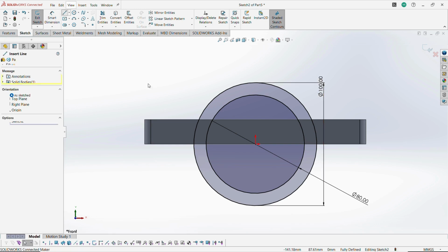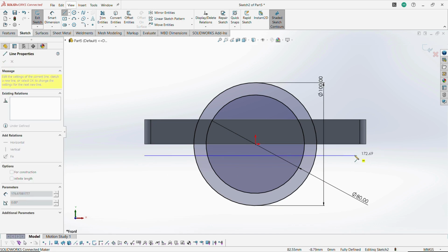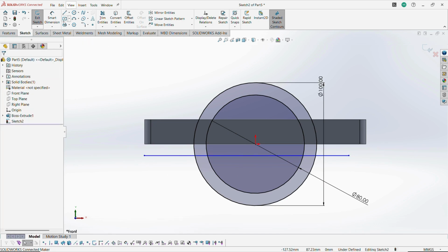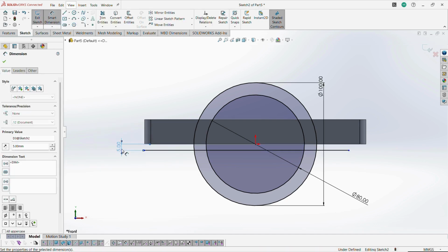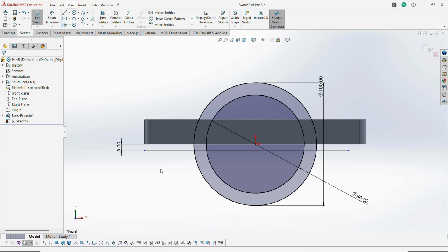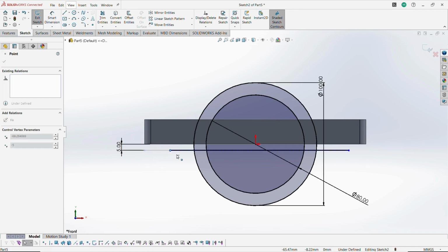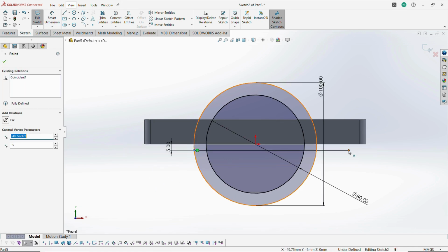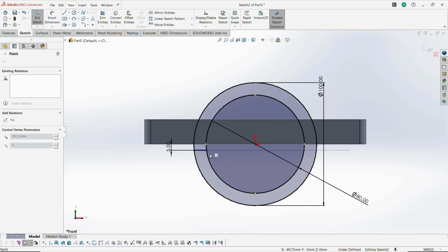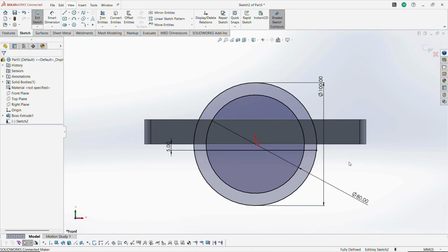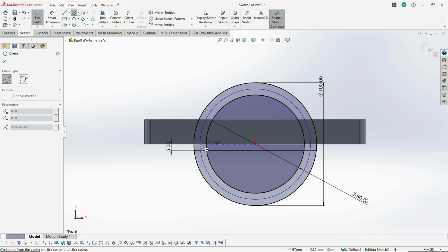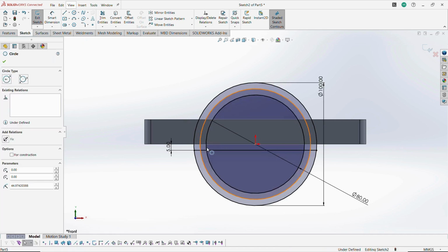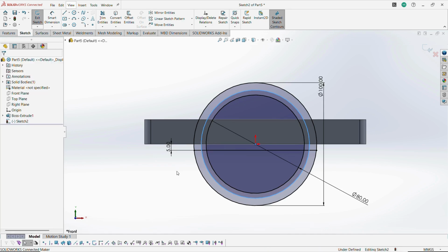So choose a line and draw a horizontal line offset from the distance of 5 mm. So mention this line offset from the distance of only 5 mm. The secondary circular profile we need to draw from this mid portion also. Once the two endpoints are closed on the two opposite circular ends, then draw another circle from this origin and place it at the middle of these portions by offsetting the distance of 5 mm.